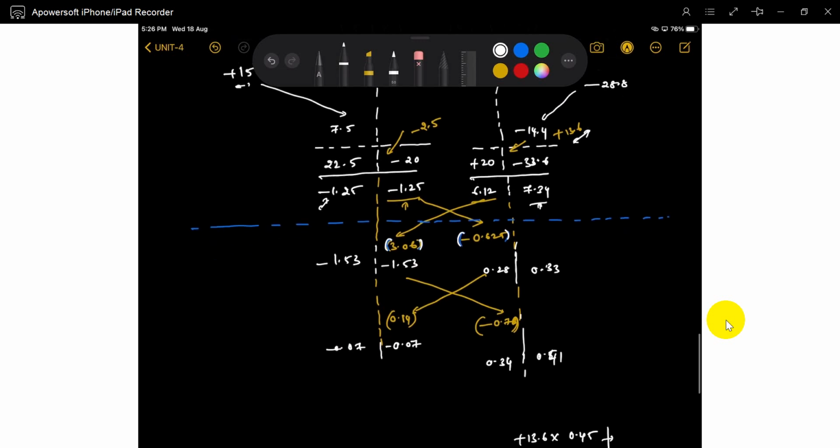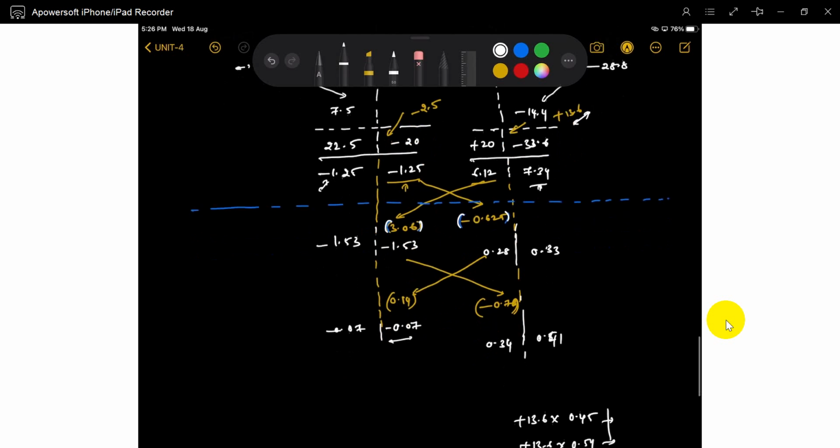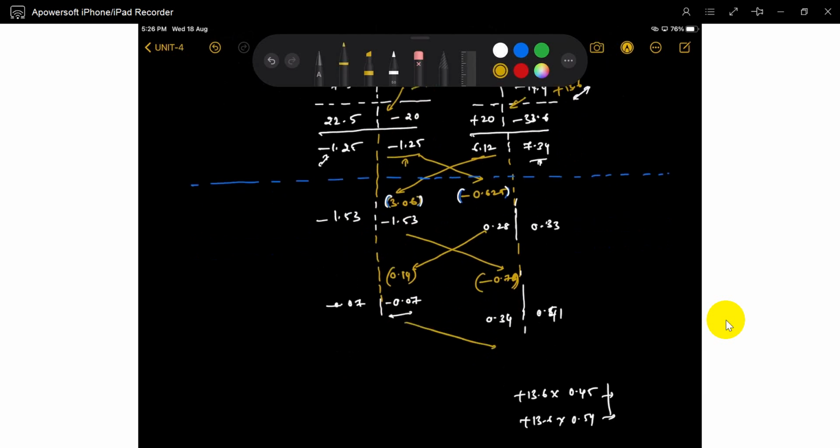Okay. Because if you see, 0.07 is very small. Take the carryover factor, again we will get a carryover moment. But these are very small. So you can reduce or you can stop it there. No need to distribute. 0.035 will come now. So again the 0.035 we can distribute between the two, very small changes. No need required. So we can stop at 3 iterations. Otherwise, if you feel those are minimal moments, you can stop it. So no need to write this.